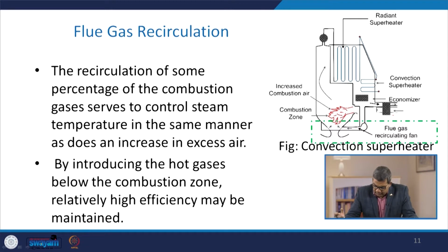Let us talk about the flue gas recirculation. The recirculation of some percentage of combustion gas serves to control the steam temperature in the same manner as does an increase in excess air.